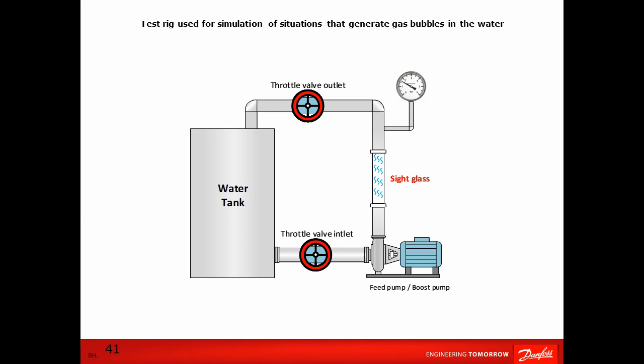We mounted a glass tube on the outlet so that we could observe the gas bubbles released from the pump. It is important to keep in mind that the test results were achieved using a multi-stage pump, whereas a single-stage pump would likely deliver a much poorer performance.